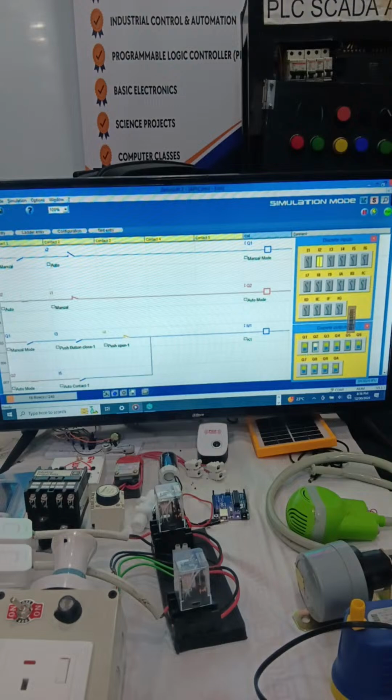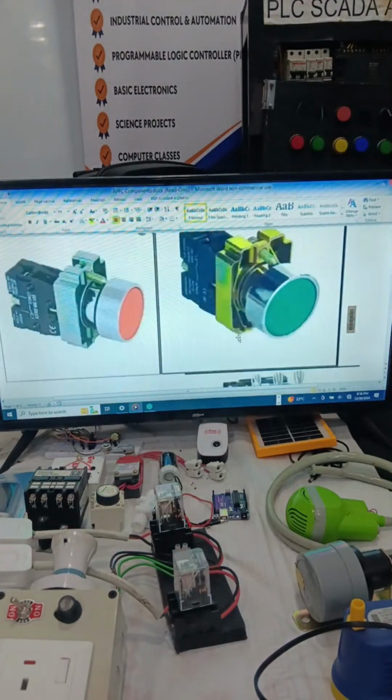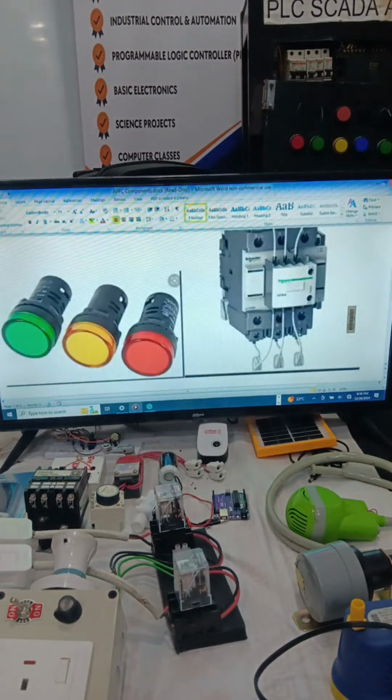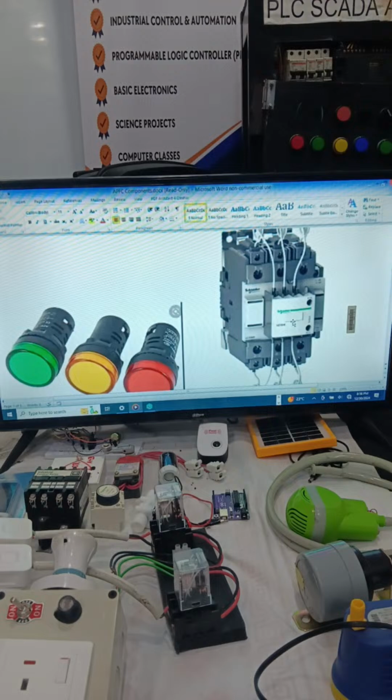Now this is in our diagram. You can see these are the push buttons. When you press this, the wire is considered here. This is spring operated. This will be closed momentarily, and this is one NO contactor. This is NC contactor. So these are on and off. Then these are the contactors which give power to the capacitors. This is a special duty contactor called the capacitor contactor.